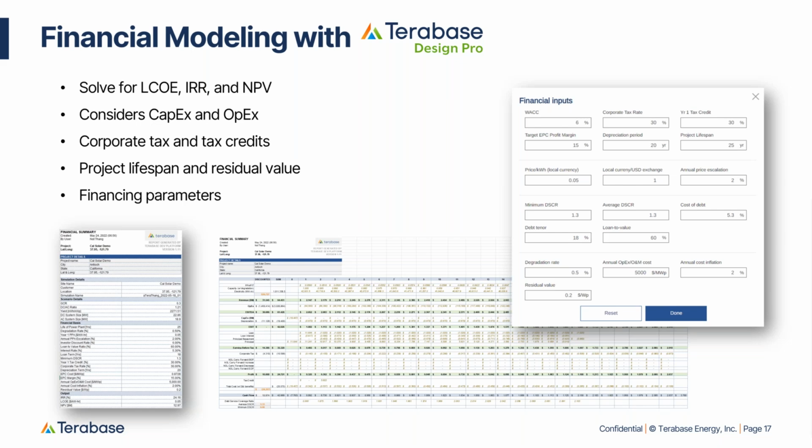The cost estimate and the energy yield report are then passed into our financial model, which allows you to solve for LCOE, IRR, and NPV. You can once again use Terabase defaults or input your own financial assumptions, including weighted average cost of capital or project life. Since each scenario is run independently and the results are unique to that scenario's configuration, you can order your scenarios by LCOE, cost, or yield and determine the optimal project input parameters for your site.